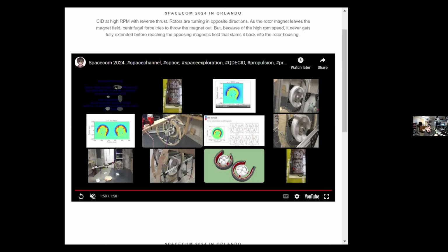So my next question is, do the magnets on each of those rotors, I assume then they need to be in phase with each other? You can't just spin these things by themselves. They have to be locked together. No, they can spin at any RPM because the thrust coming out is sort of like this, but it averages like almost a straight line. So even if they're off, the RPM speed's not perfect on both of them, it doesn't matter. It still just drives along. And in our recent tests, we'll run one rotor at a higher RPM speed and the other one at a lower RPM speed, and I can drive it like a tank. Interesting.